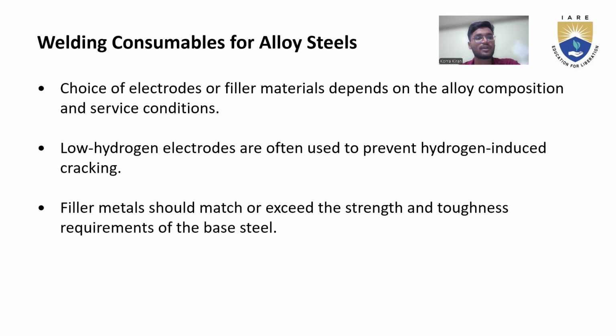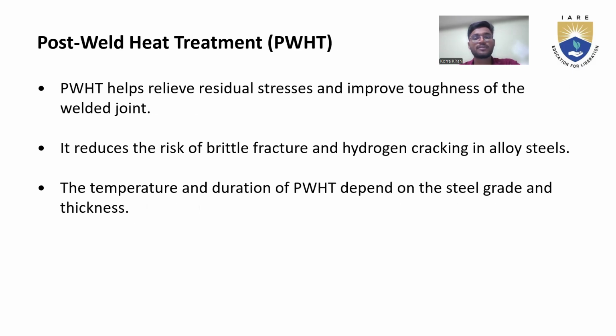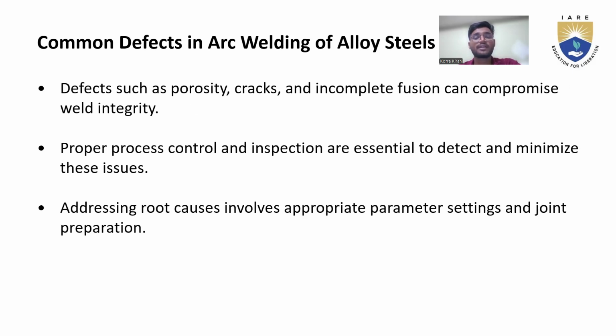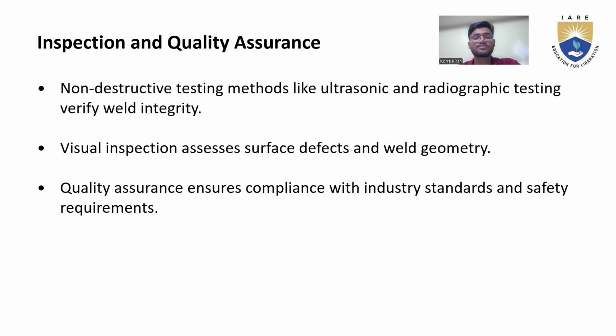Post weld heat treatment improves the toughness of the weld joint, and the risk of brittle fracture and hydrogen cracking in alloys is reduced. Common defects are firstly cracks, and also weld integrity issues. And inspection and quality assurance means that while we are doing this welding, we use non-destructive testing methods like ultrasonic or radiographic testing to verify the weld and avoid defects.